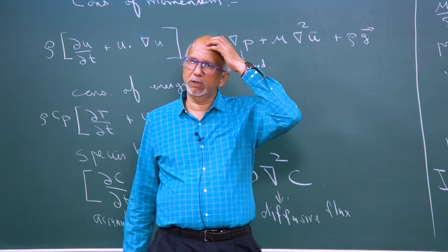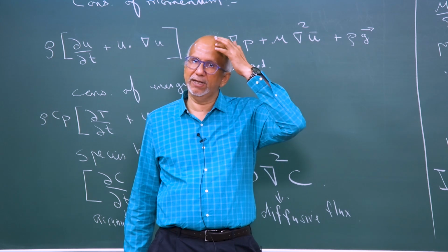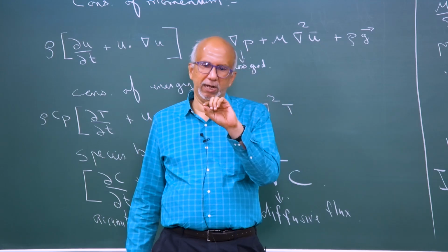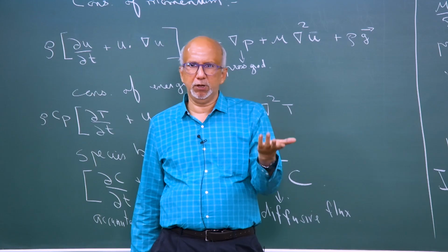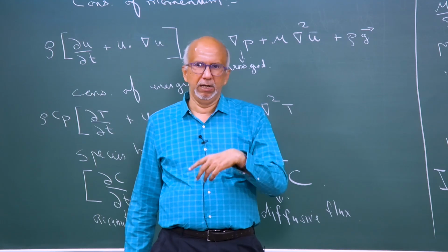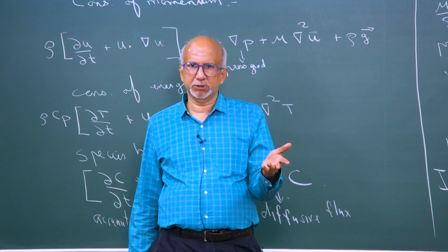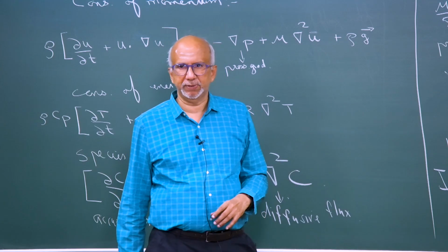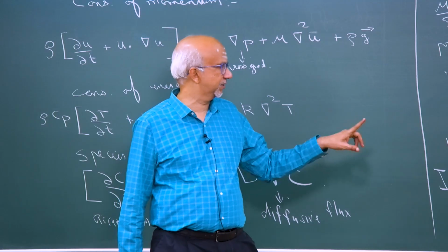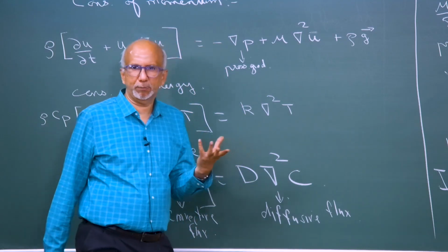Like for example, you have Joule heating. Joule heating, what is happening? When you have electrons going through a conductor, heat is being generated. That is because of friction, the electron is moving and there is some resistance to it. Okay. So, similarly an equivalent of that is viscous dissipation. Viscous dissipation is something that will always be positive.